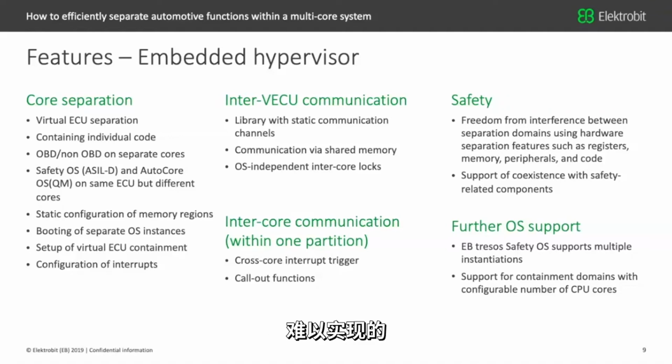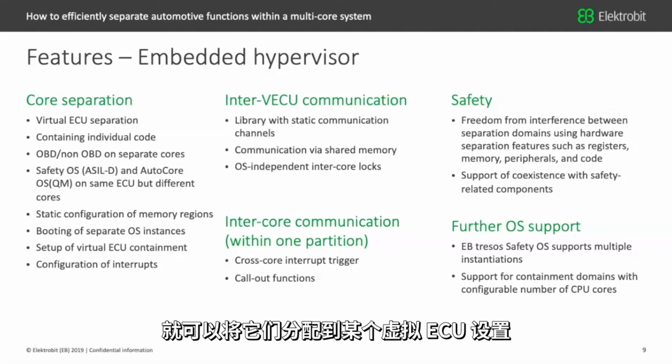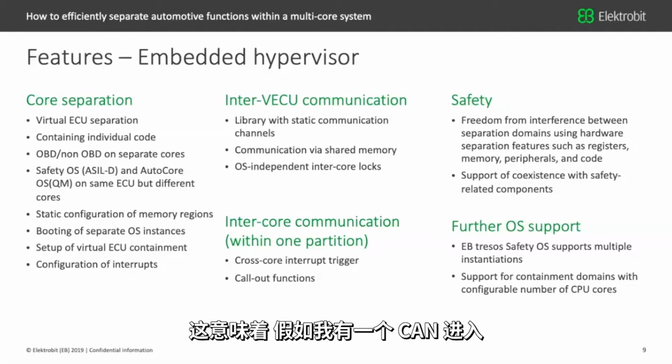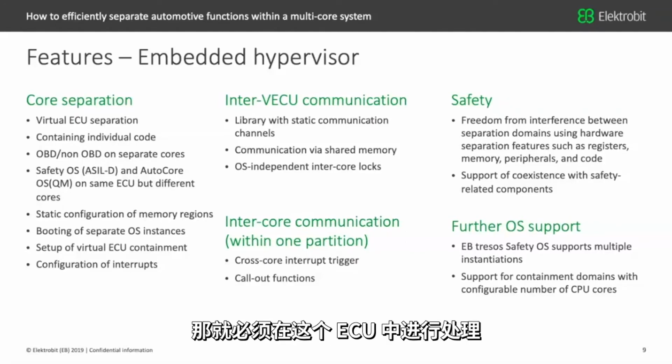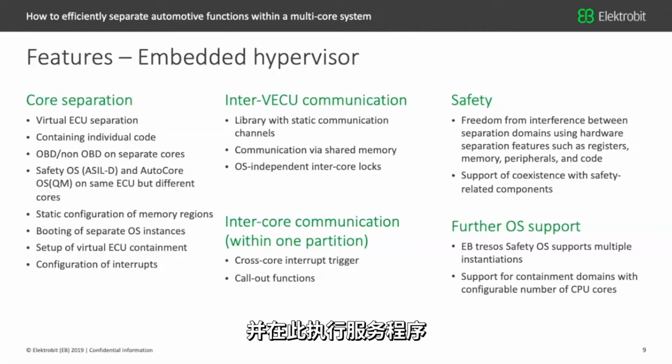One important part, and technically a difficult one to achieve, is the configuration of the interrupts. If I have general purpose interrupts or interrupts coming from whatever peripheral, they can be assigned to a certain virtual ECU setup. That means if I have a CAN interrupt, for example, it is assigned to a certain virtual ECU, and needs to be handled within this ECU and the service routine executed in there.